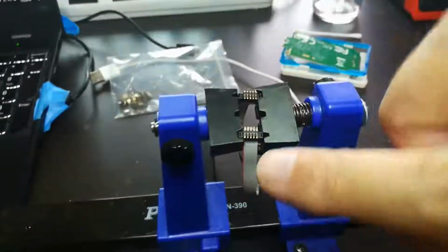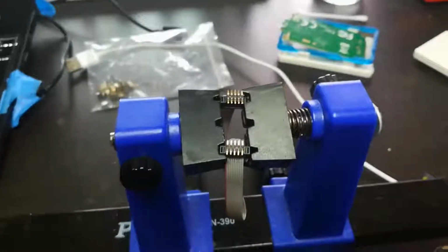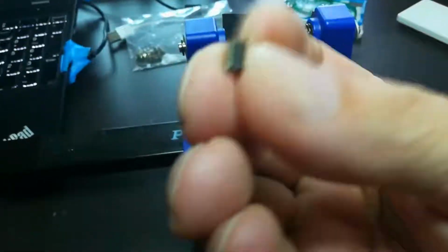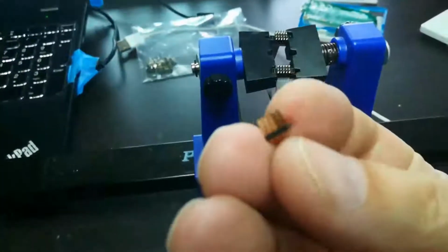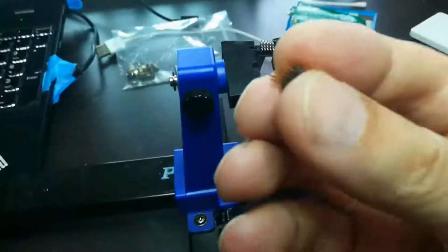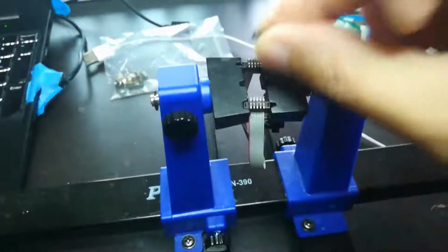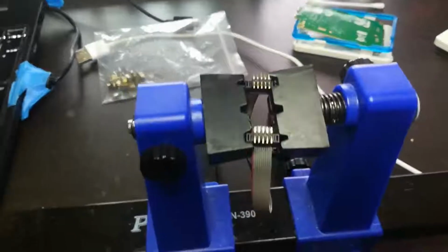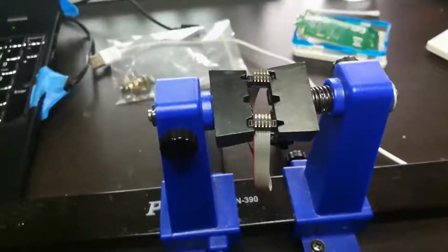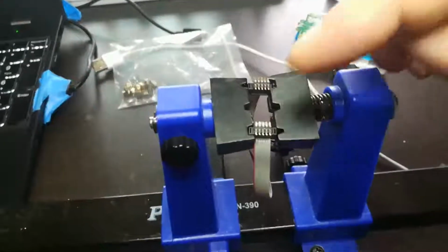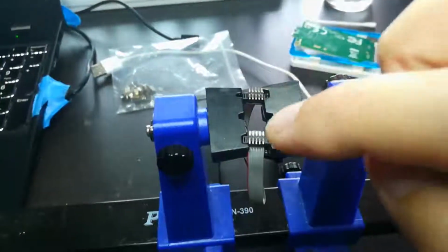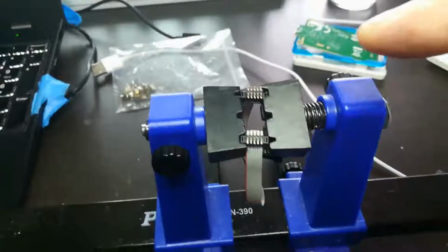Well, before I did major surgery on the cable, I realized that I have these little connectors that I solder onto the board. What if I plug these into the ends of the cable and then buzz the cable with my ohm meter to see what happens? And the cable's okay. Sad to say, each pin is connected to only its corresponding pin on the other side.